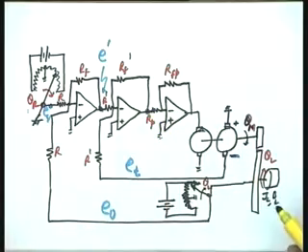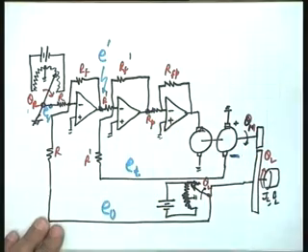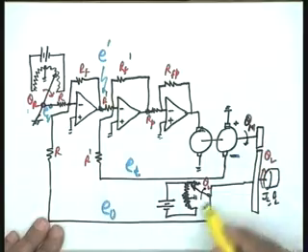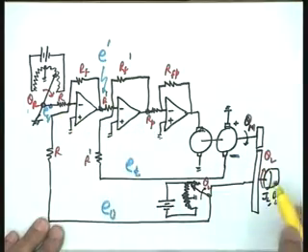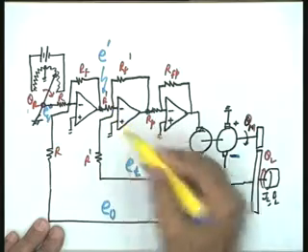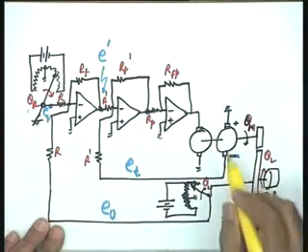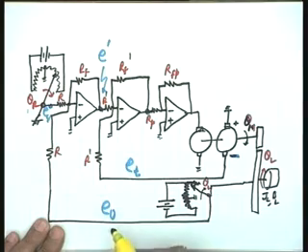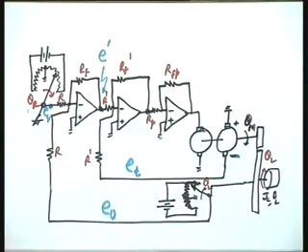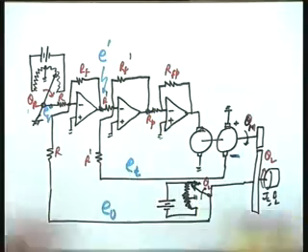So, it means now you are going to have two loops, it should be clear. One is the primary loop, which is the feedback of the position, and this is the secondary loop or the minor loop, which is the feedback of the velocity. So, it means I am feeding back the velocity in addition to the position as far as this total feedback control system is concerned. Now, you will note again the manipulation, so that the negative sign is taken care of.